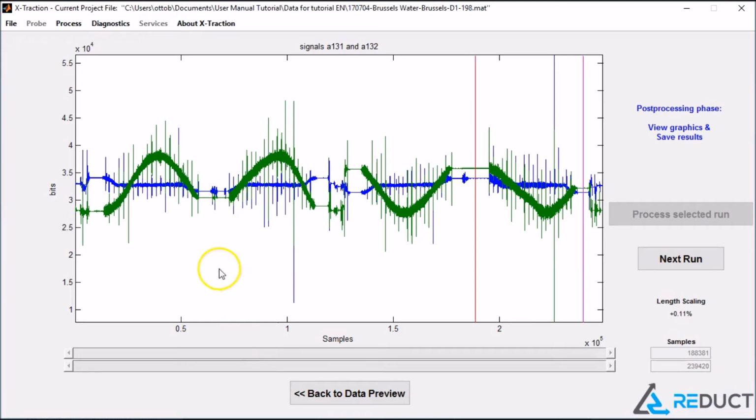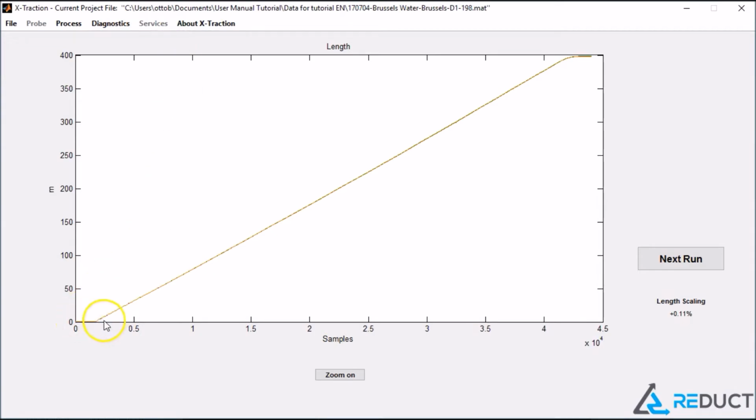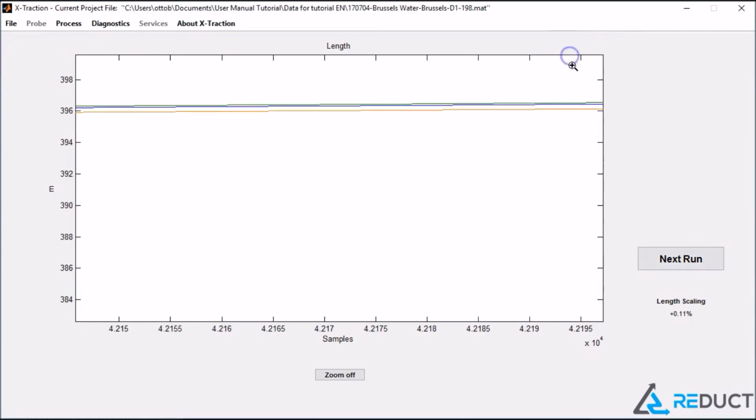After each run, you can review key diagnostics. The odometer calculation results are presented in 2 ways, as calculated pipe length traveled, and velocity. The graph portraying the pipe length traveled shows both odometer lines move in unison, indicating no slippage of wheels. You can zoom in on any section of interest. The blue line is the best fit used by the software.